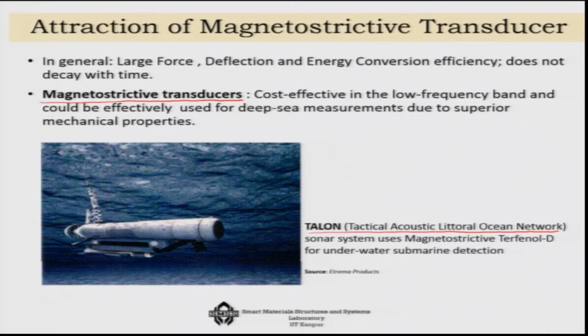If you remember, earlier we used piezoelectric composites. In this case we are using a magnetostrictive material. Let us say this is a block of magnetostrictive material which a wave is hitting. We expect this material to vibrate in this manner. As it is vibrating and mechanically deforming, its state of magnetization is changing. If we have a coil like this, which we call a pickup coil, the state of magnetization in this material changes because of its change of length.